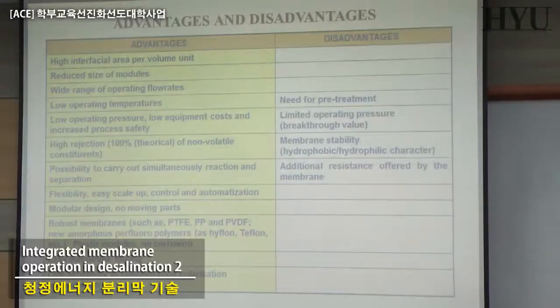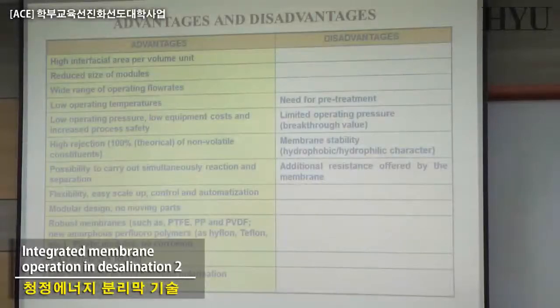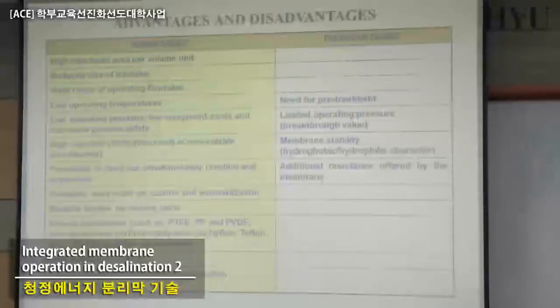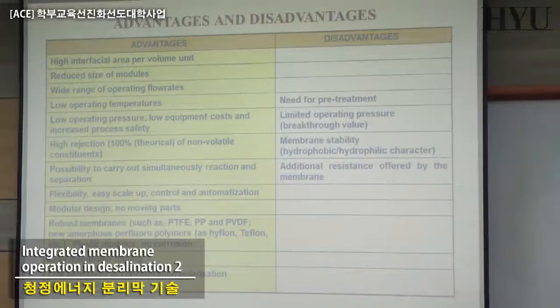Polypropylene, which is hydrophobic, if it interacts with tensioactive surfactants or with some alcohols, is losing its hydrophobic character and is becoming hydrophilic. And if these membranes become hydrophilic, they don't work anymore. So there is a new kind of fouling. We have PhD students working today whose thesis is the fouling problem in membrane distillation. Nothing to do with the traditional one, but a new form of fouling that we have to learn how to handle, to solve, how to change the pretreatment eventually.